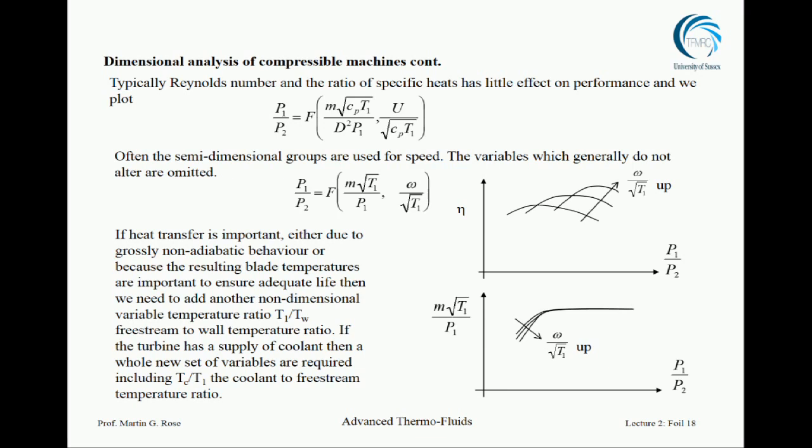You use it when you land. It's called a thrust reverser. For 5 seconds, 10 seconds, the flow is backwards. That is not backwards through the engine, but it comes out of the engine, turns around and goes backwards like this. And that makes the thrust backwards. And so the plane slows down rapidly.